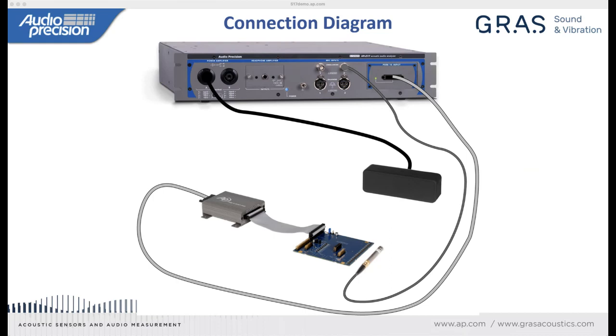And so how do we position the reference microphone both at exactly the right spot and so as not to interfere with the acoustic sound field around the microphones you're trying to measure? So the answer, if you will, is really a little bit more complicated, but it really comes down to what is the highest frequency you want to accurately measure.